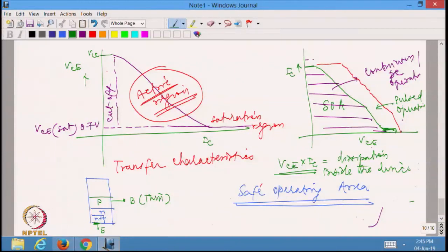Okay. Then after that I am going to have one more N inside which I am going to have again N plus, that is heavy doping. So, this particular portion is going to correspond to the collector. Normally, we call this region the drift region. This drift region is going to offer some amount of resistance. The longer the drift region, the resistance will be somewhat larger.